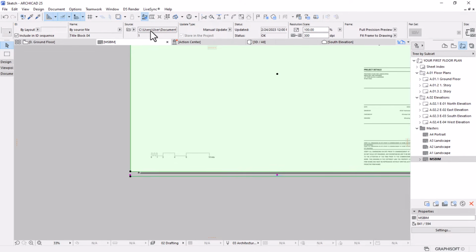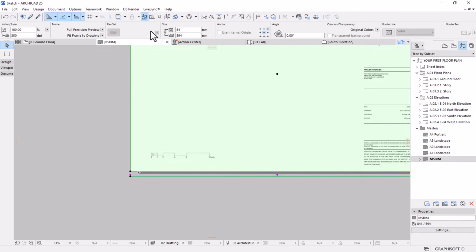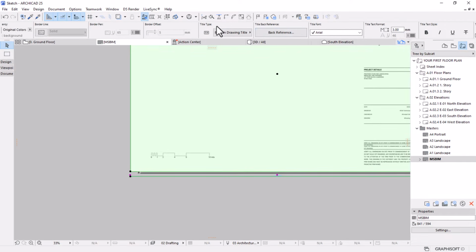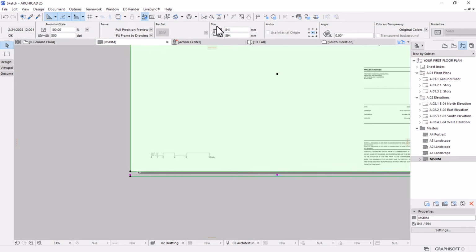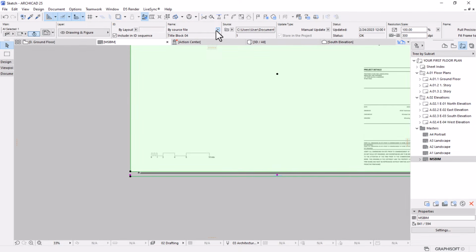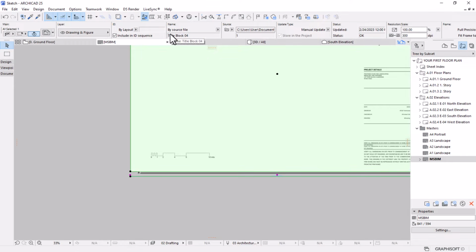This section, you see, if you scroll your mouse like this, forward or even backward, you would see this info section with parameters that are specifically for the actively selected element. So if you were to select a wall, for an example, a wall element within your file, it will only display the parameters for the walls. So it's dynamic because it depends on what is being selected within your ArchiCAD.